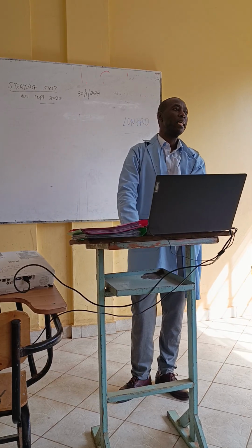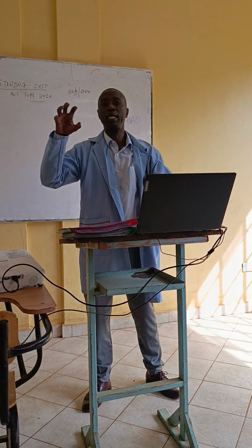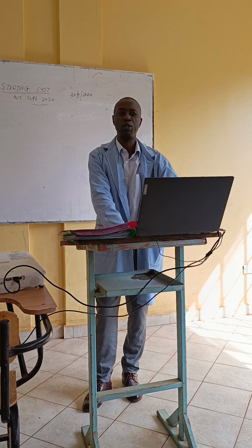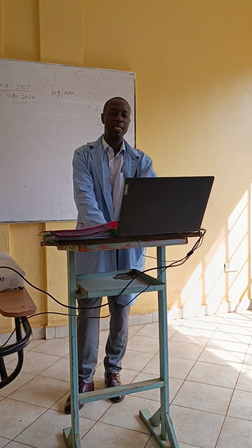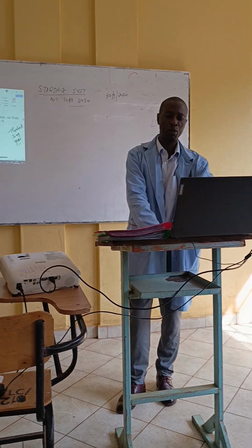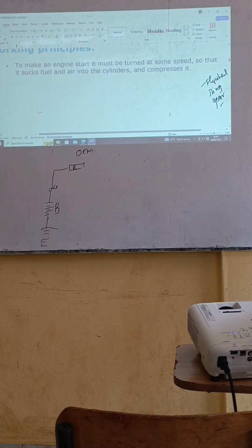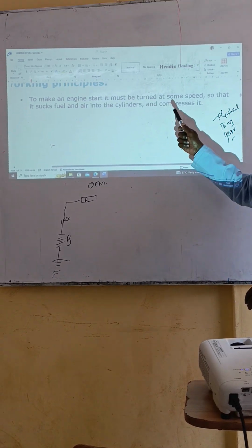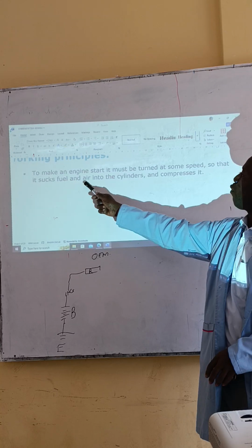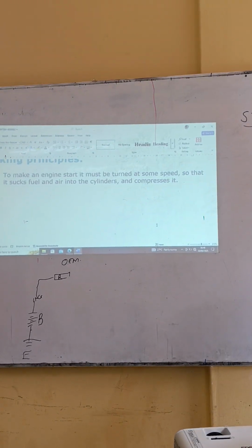Now, lastly, if you're going to be asked about the working principles, how does the starter motor itself work? Just give a brief one paragraph explanation of that by saying that to make the engine start, I'd like to magnify this a bit so that you can see. So to make the engine work or start, it must be turned at some speed, so that it sucks fuel and air into the combustion chambers and compresses it again.